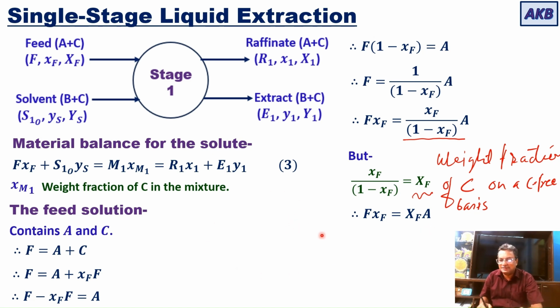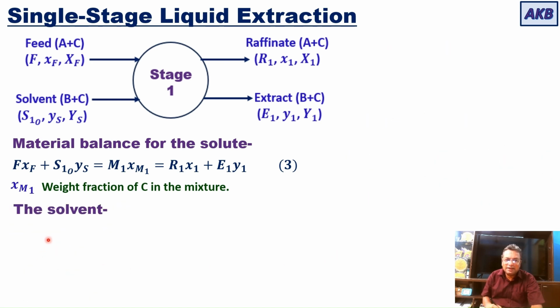Okay, so what we have understood is that we can replace the term F into XF with capital XF into A. What is capital XF? Capital XF is defined in this way, and it is the weight fraction of C on a C-free basis in the feed. Now, let us analyze the solvent phase.